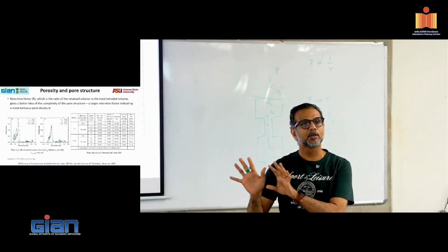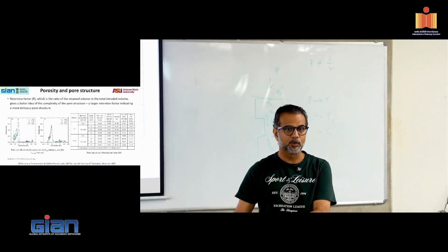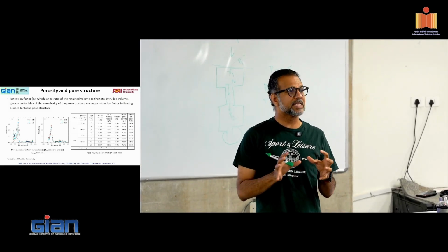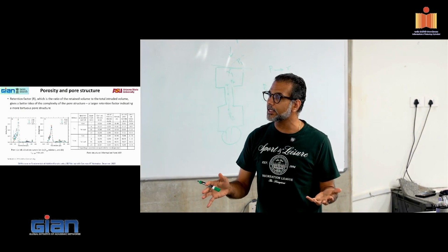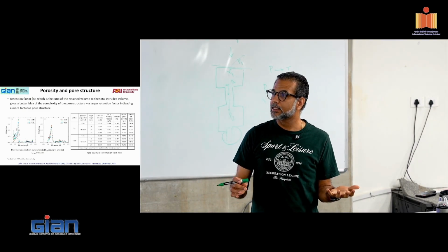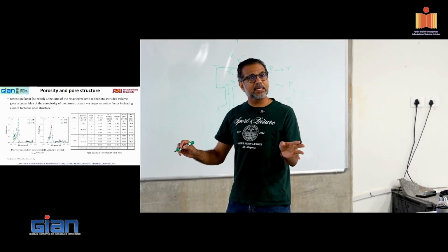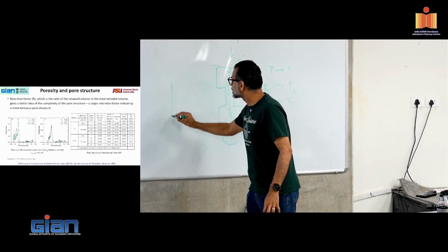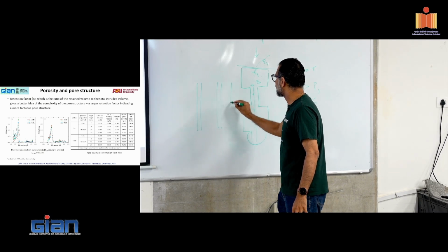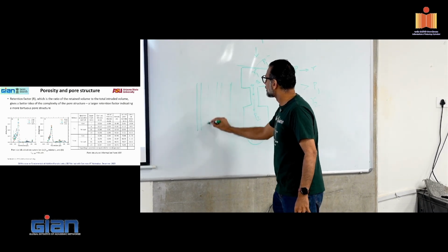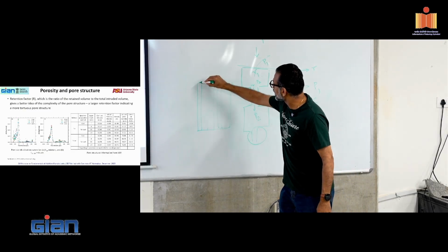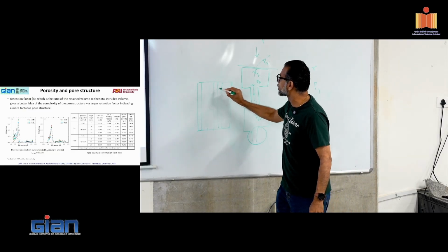You see, some mercury stays back in the pores. So that is called the retention factor. How much of mercury is retained in the pores? And why is mercury retained in the pores? Because the pores are not of the same size, whereas the basic theory of MIP assumes that all the pores in your concrete are cylindrical, of different sizes, but will traverse the entire length of your sample. This is what MIP assumes your pores to be.